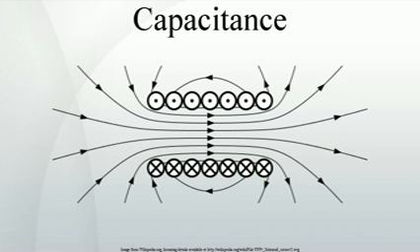Capacitance of nanoscale systems. The capacitance of nanoscale dielectric capacitors such as quantum dots may differ from conventional formulations of larger capacitors. In particular, the electrostatic potential difference experienced by electrons in conventional capacitors is spatially well defined and fixed by the shape and size of metallic electrodes, in addition to the statistically large number of electrons present in conventional capacitors. In nanoscale capacitors, however, the electrostatic potentials experienced by electrons are determined by the number and locations of all electrons that contribute to the electronic properties of the device. In such devices, the number of electrons may be very small, however, the resulting spatial distribution of equipotential surfaces within the device are exceedingly complex.